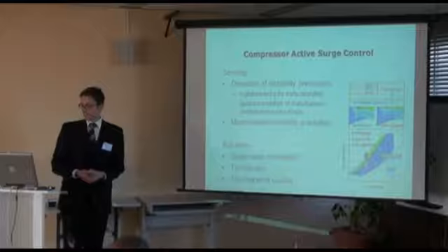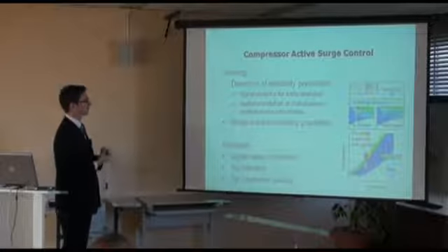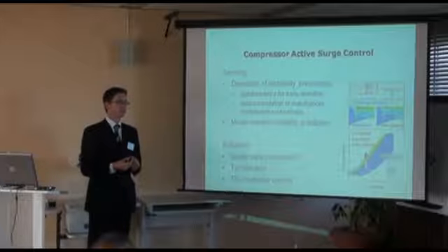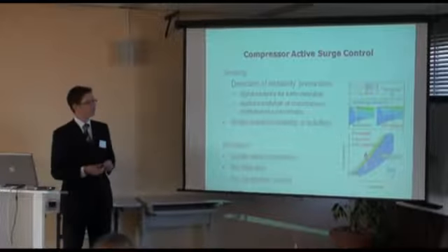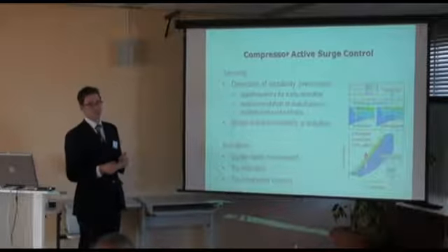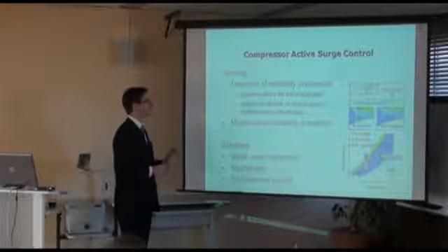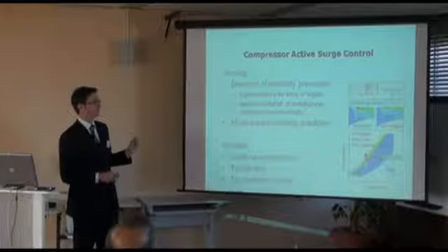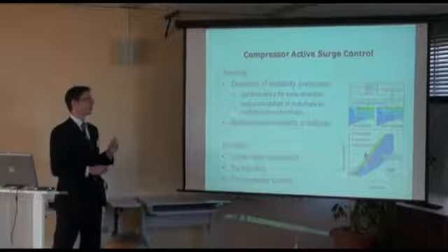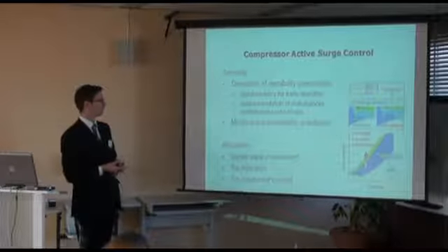So now looking at active surge control. To enhance the operating range of the compressor, you have got the possibility that instabilities go along with instability precursors, which are pressure signatures which occur before the actual instability event. And you can sense these pressure fluctuations. You need very high frequency here. You have got early detection before the event starts. And you have to consider the spatial correlation of these disturbances, so spatially about the circumference.